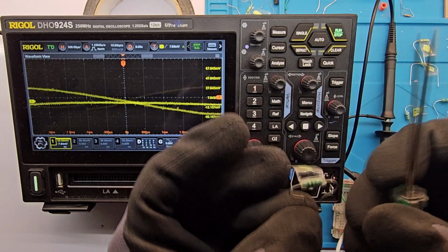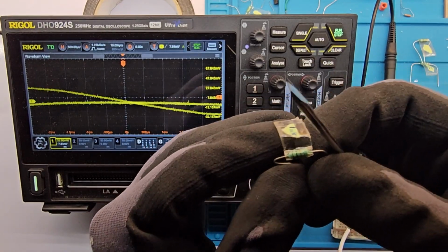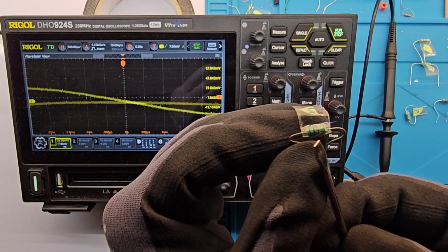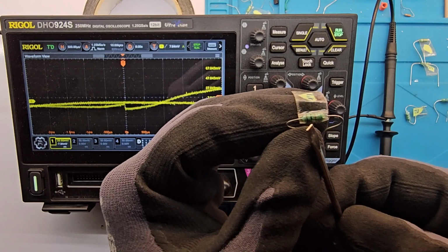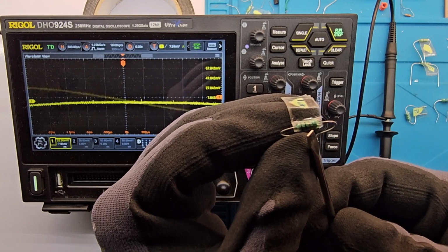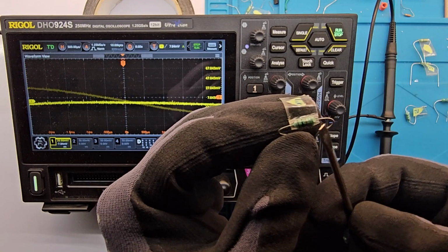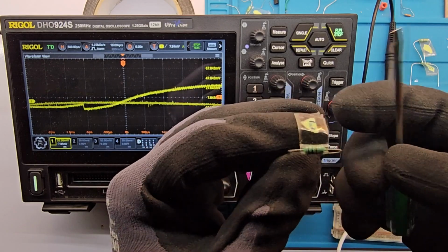So you have the brown, then black, and then red. The brown is 1, black is 0, so 10, then red is a multiplier, which is 2. So 10 and 2 more zeros, that's 1000 nanohenries or 1 microhenry.